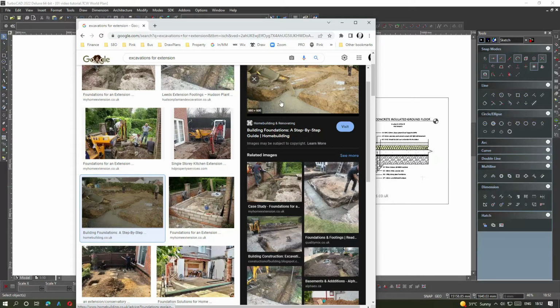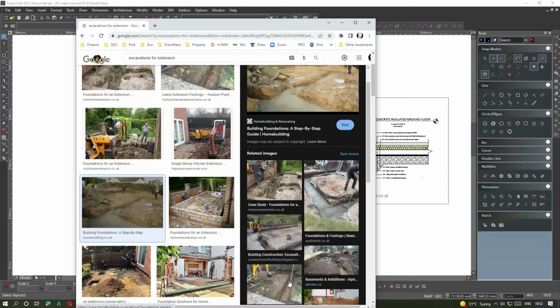Generally, if you've got quite a few cubic meters, then it probably makes sense to have the concrete ready mixed and delivered and pumped in rather than mixing it on site. It's pumped from the back of the house or from the front right the way through the house into your foundation. So it's very quick, only takes a few hours. That's a great way of getting the concrete in for the foundations.